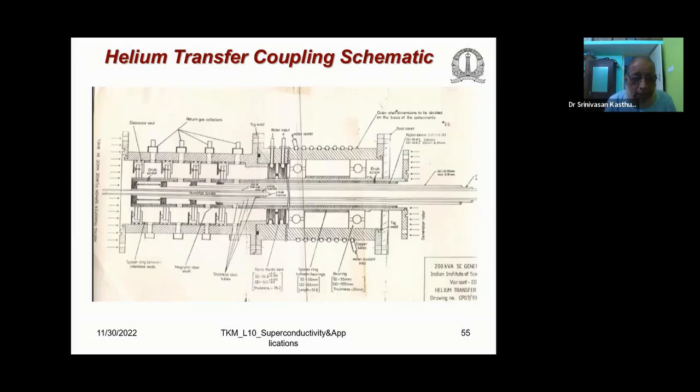So what does it contain? It contains 4 clearance seals here. And it also contains what is called the ferrofluidic seal, which separates the incoming cold fluid and the return gas. Also a set of conventional bearings is used in this place.